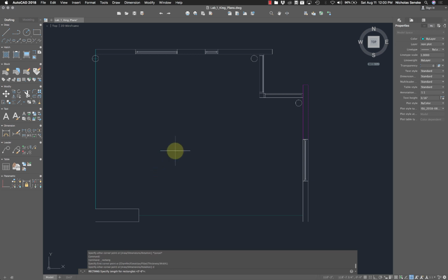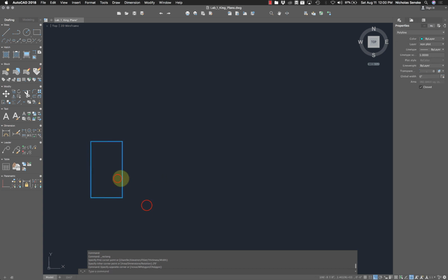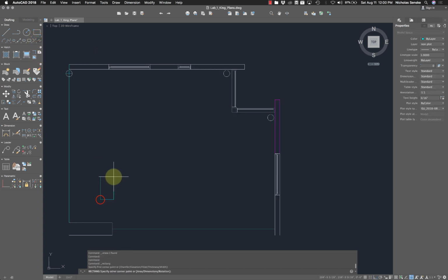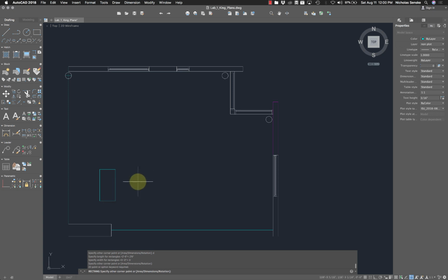Same thing. I could go dimensions. I could say 30 inches. And I could say, well, actually, I'll go back and do that. That's actually what they wanted me to do. So I could say 2 foot 6 inches. Oops, I made it the same in both dimensions there. Okay, one more time. Dimensions: 2 foot 6 inches by 5 foot. Now those dimensions are already in there too, and I actually have to press the Enter key when I'm done, or it doesn't stop the command here.